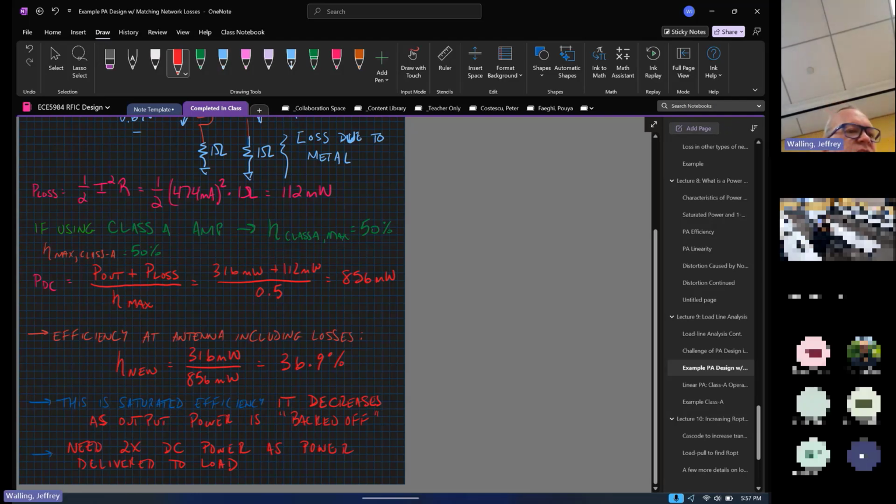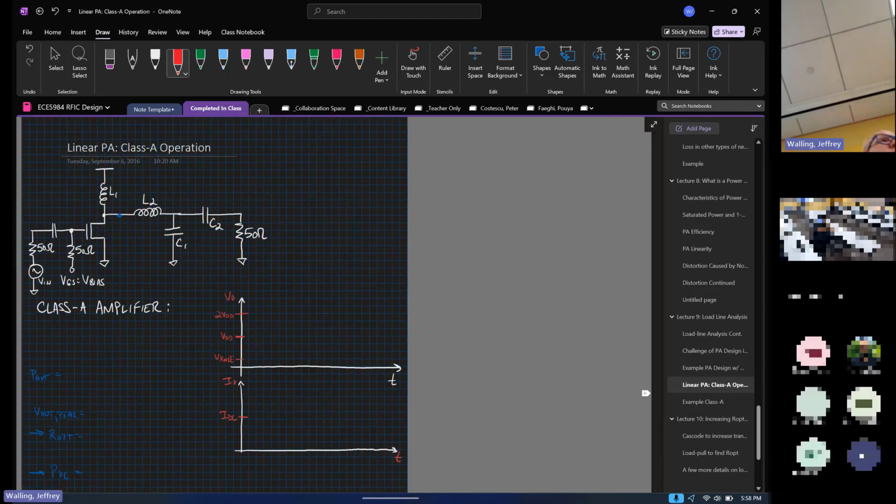All right, well, we are making things in CMOS. CMOS does have advantages because it's scaled at a much more aggressive rate than gallium nitride or gallium arsenide have. It's smaller, and so it has shorter channel lengths, which typically means it's faster. So we can't necessarily make higher power, but we can make higher speed or higher frequency amplifiers. Is it cheaper? CMOS is way cheaper generally than 3-5 devices.